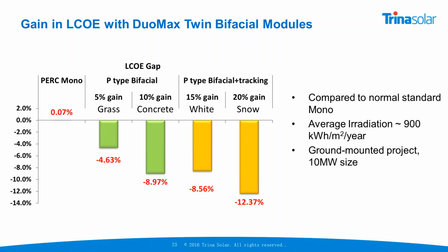So when you have a module that is not bifacial, on the front side you usually have uniform sunlight, unless there are bird droppings or leaves or soiling on the module. But in general you have very uniform illumination. On the back side it's not always the case, due to the nature of the reflector of the background, the surroundings, the rack design, etc., and the position of the sun. You may have not-so-uniform light on the back. It's true, and so a situation of hotspots could happen.